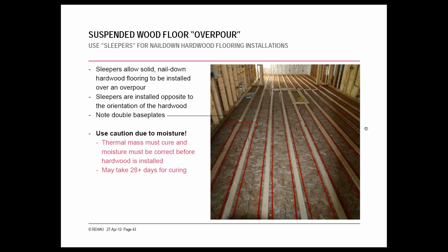One thing with these wet over pour installations, depending on the type of floor covering you're going to be putting on top, this is usually just a residential application, but you may need to install a sleeper to give you something to nail to. So if you're going to be putting in wood floors, you obviously would prefer not to be driving those into the overpour. Now, a lot of the engineered wood floors these days are floating, so that's not something you would have to accommodate for. But if you're using a traditional nailed down wood floor, something you need to take care of would be installing sleepers before you do the overpour.